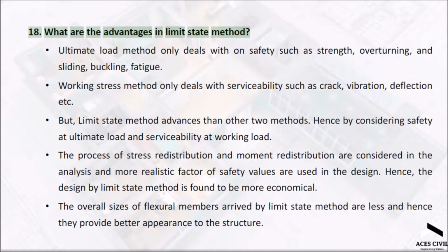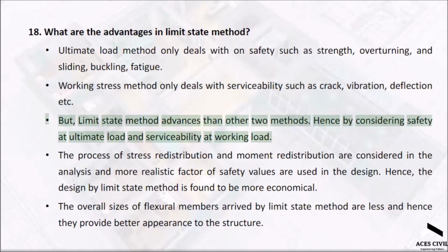What are the advantages in limit state method? Ultimate load method only deals with unsafety such as strength, overturning, sliding, buckling, fatigue. Working stress method only deals with serviceability such as crack, vibration, deflection, etc. But limit state method advances than other two methods.